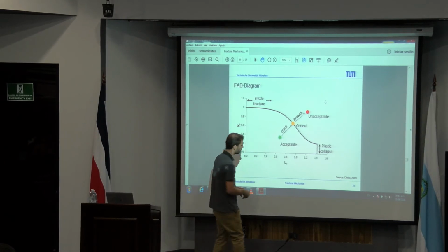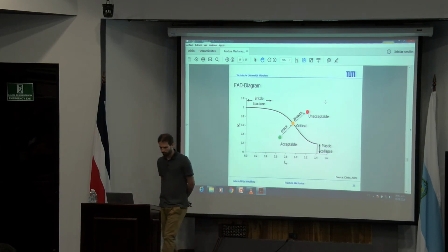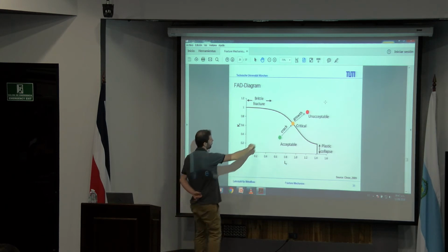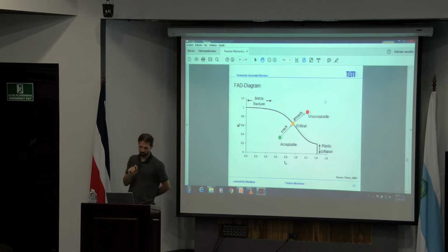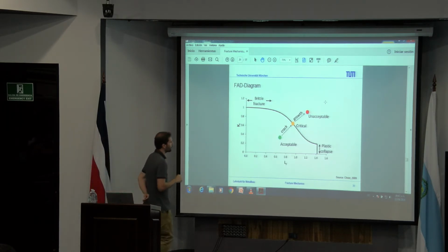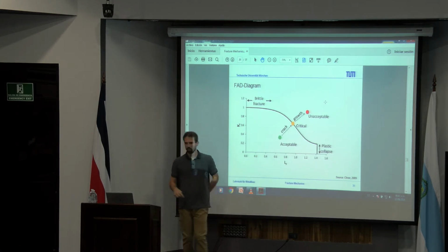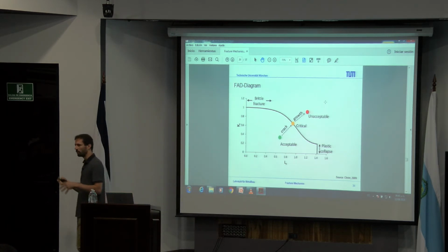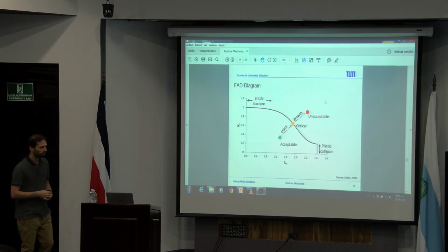So the yielding point, of course, would always be here at this level. This is described by the R6 option 2. And so, for example, if you're here, for example, at the green point, this is something where you go out for some inspection of your structure, of your bearing system.